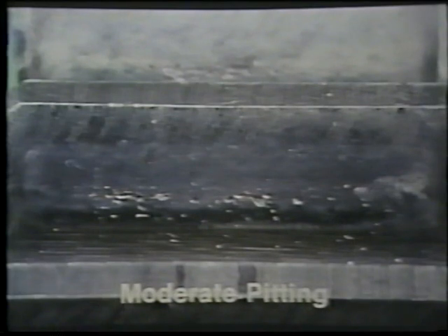Signs of changes or distress on gear tooth surfaces may suggest that a gear needs replacing, but most often these surface changes may actually heal over with use. Gears that appear to be getting ready to fail may give many more miles of trouble-free service, especially if the transmission is going back into the same type of use.